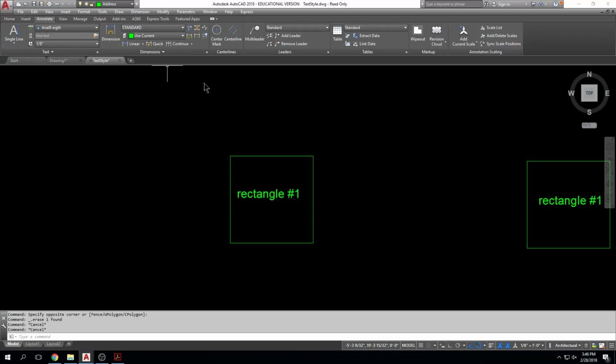We now have an annotative workflow so that we can create essentially 1, maybe 2, if you want to have a different font or a different text height. But we have the ability now to make 1 or 2 different dimension styles, and AutoCAD changes the height of the text to fit the scale we're using. Essentially, so nice, right? And that's what's really nice about the annotative quality, right? We have 1 dimension style, and the text flexes depending on the scale we print it at. It's great.